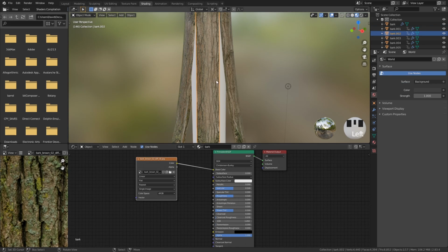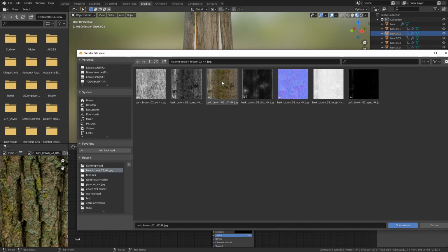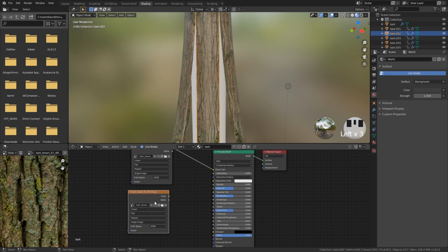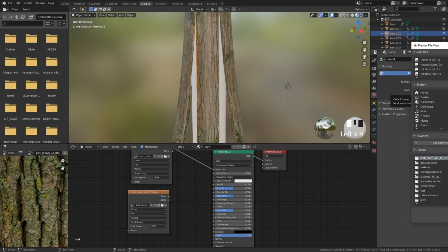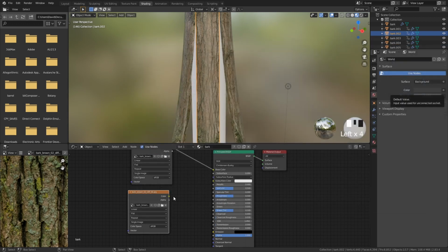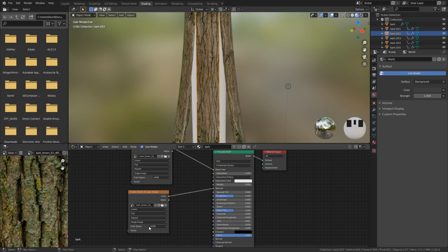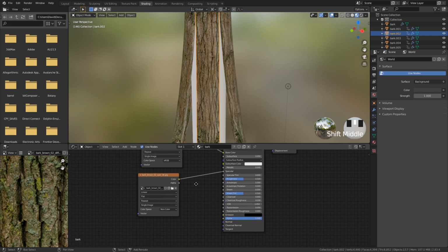If we look at the textures that we have here, we of course got this diffuse. We also want a normal, specular, and the roughness. And they're very simple. You can just duplicate this image texture, then open the specular, color goes into the specular, and then of course the specularity is like a non-color data, so change the sRGB to non-color. Then just duplicate it over again.